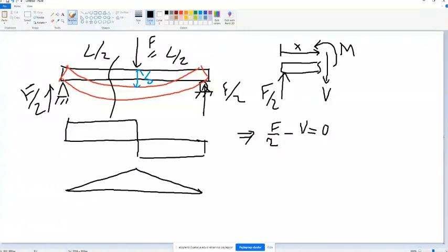And when you look at the bending moment, I'm going to explain it. We will have something like that. How? Because of the equations. Now, if you integrate the force equation, you will get the moment equation. This is the first way, which means when you calculate the area below this, you will get the top or the end part of the moment value. This is the area method, the second one.